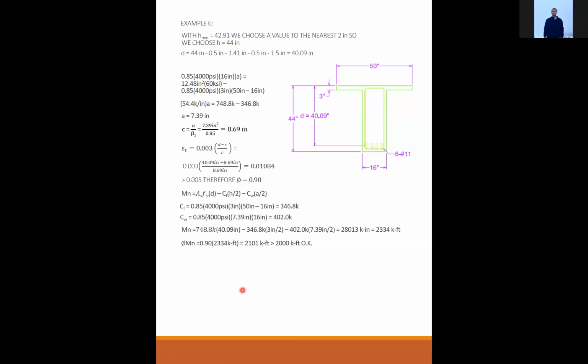Sir, could you repeat why was 0.01, why was our delta T? Yeah, okay. Well, because when you have an initial target, you have so many unknowns. We didn't know the width, we didn't know the depth, we didn't know how much steel we needed. So we needed a target. Now, I suppose this being significantly less than 0.125, I could have gone, well, okay, we need to go a little bit deeper.